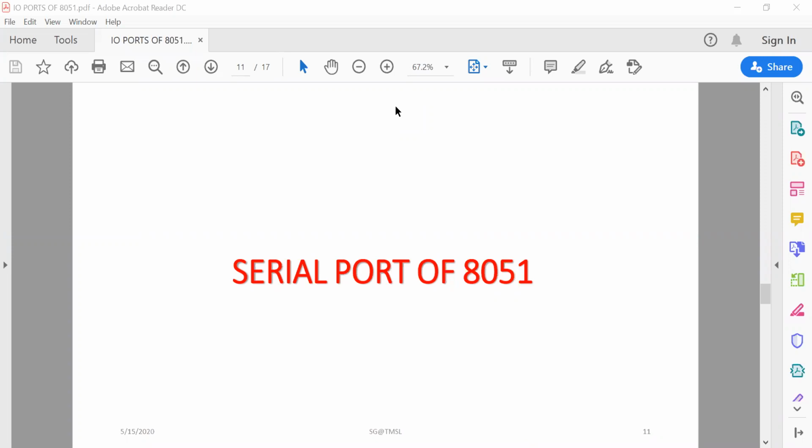Another register is the serial control register, in short called SCON. This SCON register is actually the control and status register, programmed to configure bits contained in one serial word, the baud rate, or the synchronization clock source. It also contains status bits that indicate whether the data is transmitted completely and whether any new data is received.